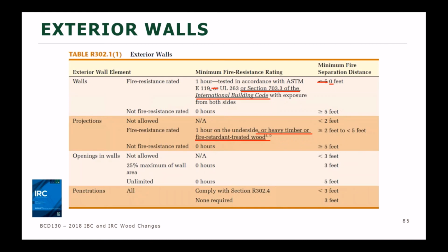Lastly, penetrations. If they are within 3 feet of the lot line, then you're going to need to protect them. If they're more than 3 feet from the lot line, then they're fine without any additional fire protection.